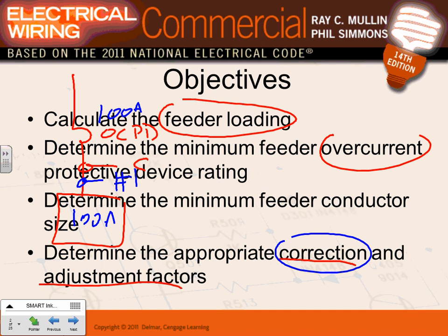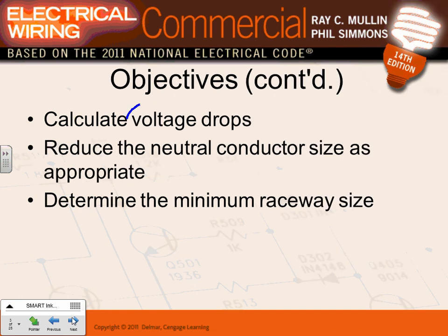Calculated voltage drop. I promise you guys, I will do voltage drop calculation a little bit. When it comes to feeders, there are a couple of things you have to be very aware of. Number 1, you guys size the cables for me, no problem. We size the cable based on the load. Number 2, we have to size it based on the voltage drop. We didn't talk about sizing based on voltage drop, so you have to pay a little bit of attention to sizing a feeder based on voltage drop.